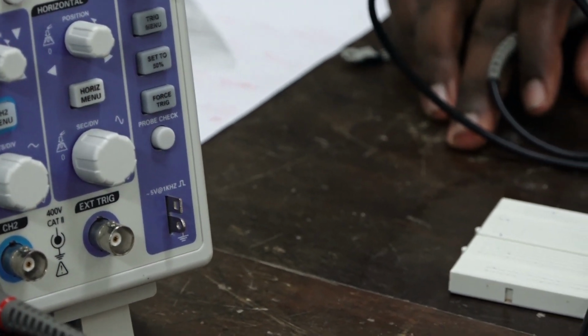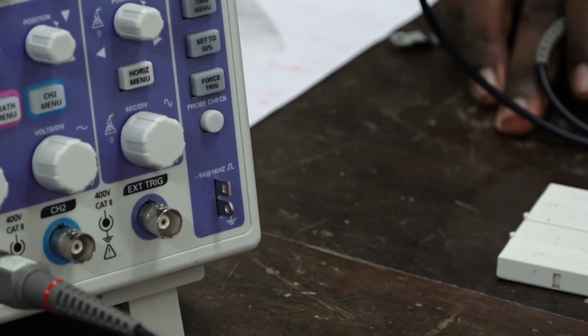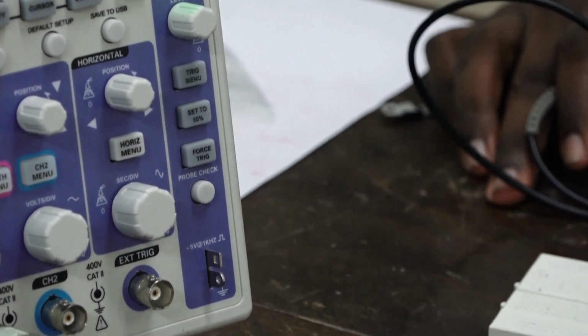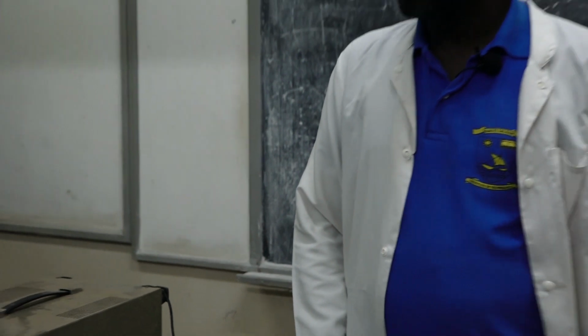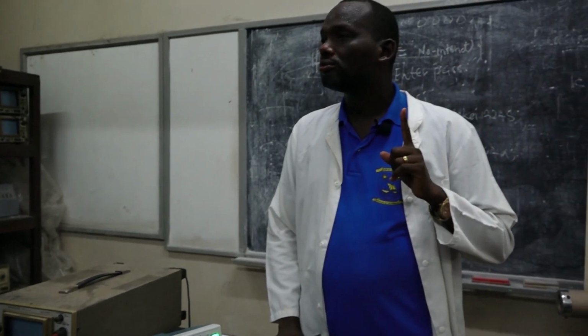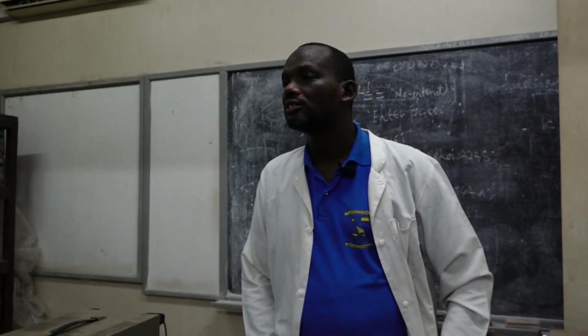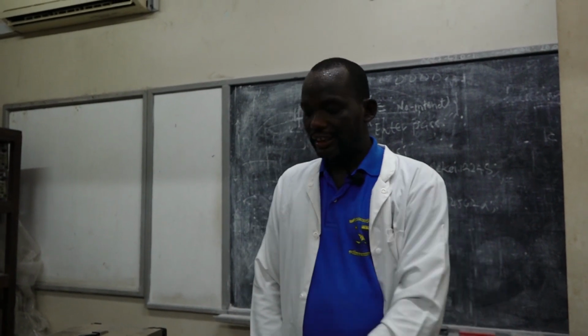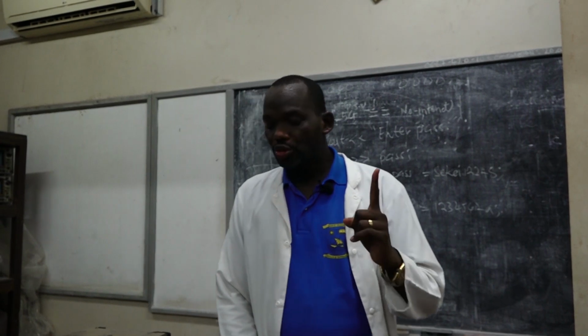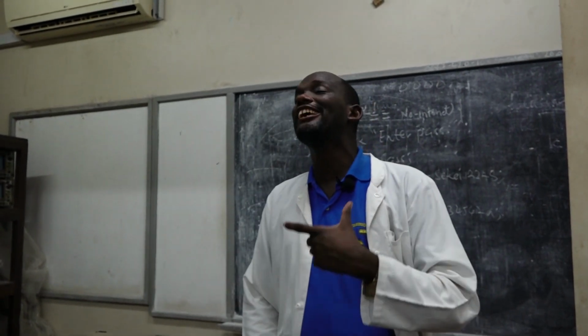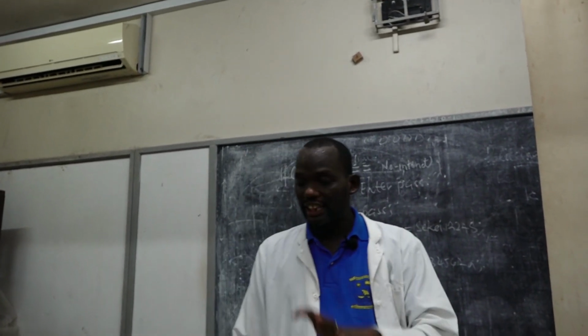It's not sinusoidal, it's not sawtooth, it's not triangular, it's not a ramp signal, it's not any other signal that you may get in the function generator. So the nature of the waveform is a square wave, a pulse. Say pulse. Then that pulse will have a maximum voltage of 5 volts, and the frequency of that pulse will be 1 kilohertz, or 1000 hertz.